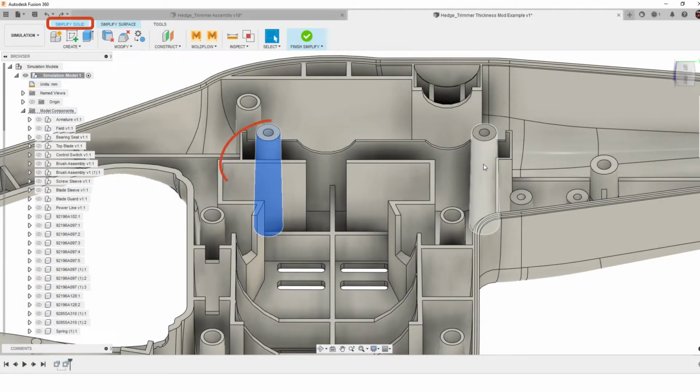Areas of the part that have thicker wall sections shrink more than areas with thinner wall sections, because there is more material that cools and shrinks. The best way to reduce overall deflection or warpage is to reduce the thickness of these thicker areas.